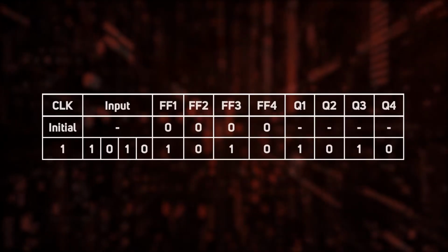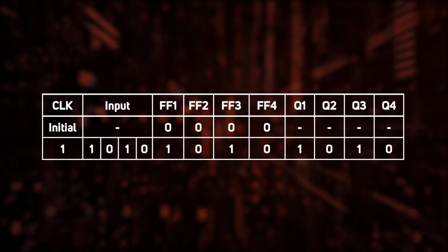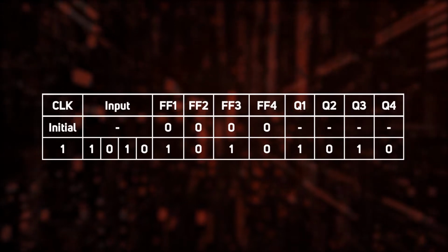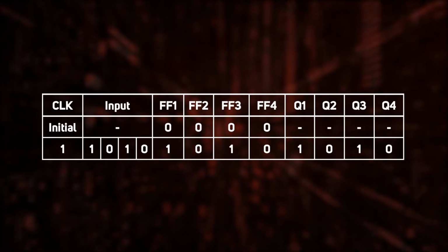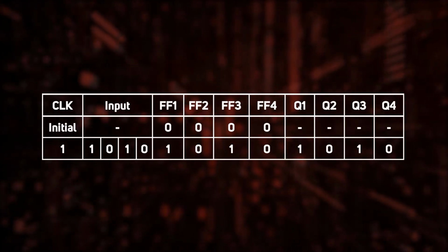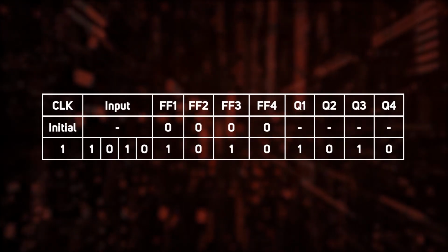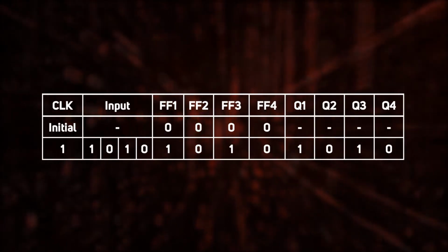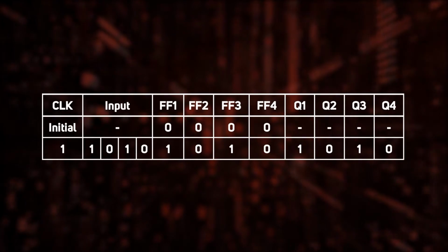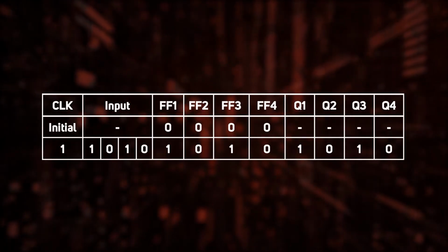See how much faster the PIPO register is when compared to the other registers. Look at the table, you can see the contents of the flip-flops and the external outputs are all set in just one clock pulse. So, we can infer one point from this, that the parallel mode of operation is faster than the serial mode. And moreover, you can load and retrieve an n-bit data word in a single clock pulse.